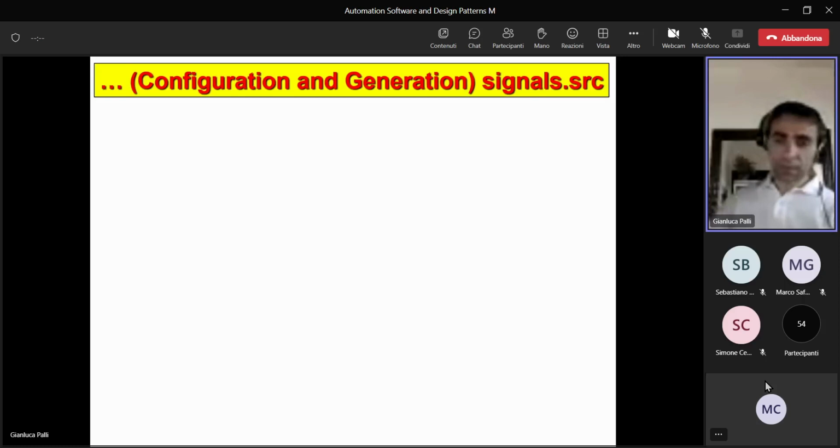So basically, this mechanism can be used to show the user what is happening and update the state of the finite state machine in some way, to let the machine know that something happened. But, for example, the stop of the machine will be driven explicitly by the hardware, because the hardware has specific safety inputs that are driven by a parallel mechanism to stop the machine immediately.